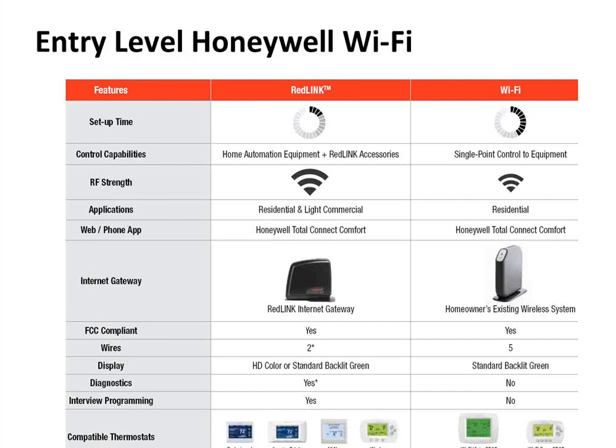The only one that's not going to do the hydronic zoning very well is the Carrier and Bryant one. For airside zoning, the Carrier and Bryant are the best because it's already integrated, no bypass dampers, all that stuff. For hydronic zoning, they don't support that. So you would need to stick with Ventstar or Honeywell or one of the other non-furnace manufacturers, if you will.